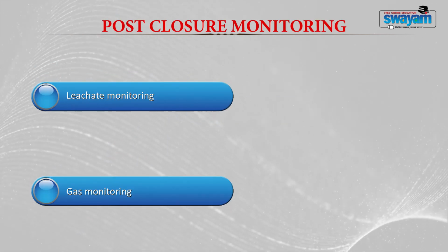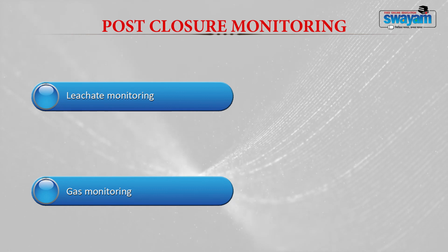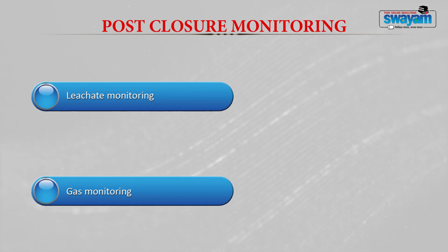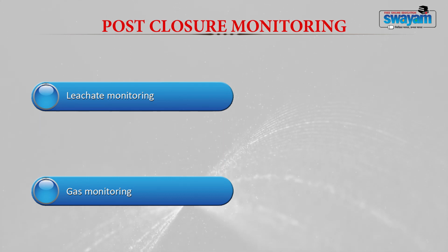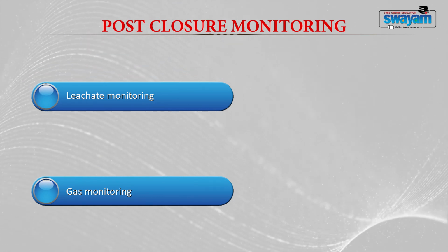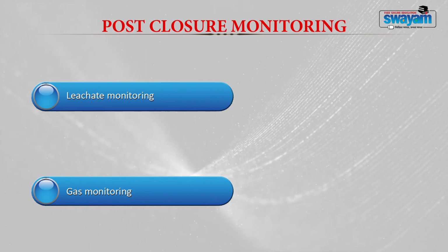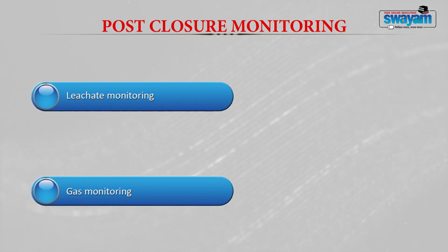Now, once the landfill is closed by sealing it with a landfill cover, it is not sufficient that you forget about the landfill. You have to do certain post closure monitoring for a period of at least 5 to 10 years. This post closure monitoring is done by leachate monitoring and gas monitoring. Throughout your landfill, you should install, during construction itself, a lot of groundwater wells. These wells should be sealed, and every fortnight or monthly you have to collect the water from these groundwater wells and analyze it to check the water quality.